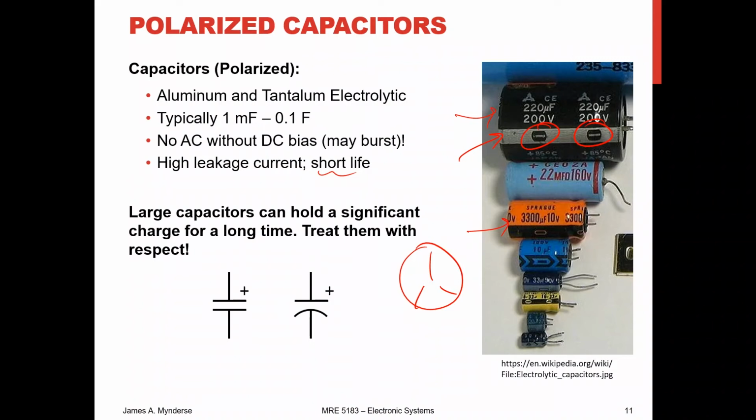So in electronics, if you start to, say, hear a hum in your speakers, sometimes it's because your driving circuit has a bad capacitor and you could replace it. But be careful with these because they can hold a significant amount of energy, and so that's a good reason to have a large resistor hanging around to dissipate the energy before removing them. If you dissipate it through your fingers, it's going to hurt, so don't touch them unless they are absolutely dead. The big ones, they hold a lot.